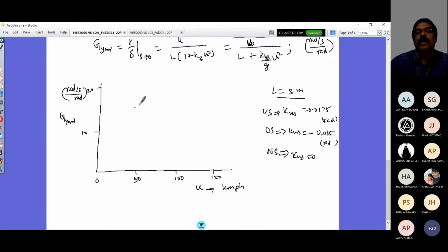I'm going to give some steering input, and you look at, for the chosen speed, what the value is at that time. So you will keep plotting it, and the variation would be linear. That's what you would see. So I'll have some speed and then accordingly my data would change. So this is the neutral steer tendency of my vehicle. This happens when KUS equals 0.